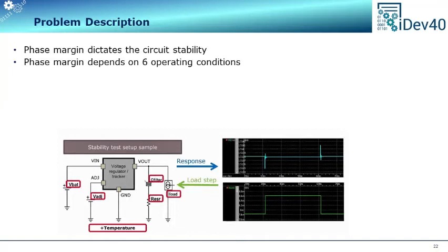In the second snapshot, it is illustrated what happens at the input of a voltage regulator, namely an impulse, a step function is applied. Then, at the output of the circuit, a very short oscillation is expected. After this pulse, an overshoot will occur, followed by an undershoot, and then it will stabilize, since this is actually the job of a voltage regulator.